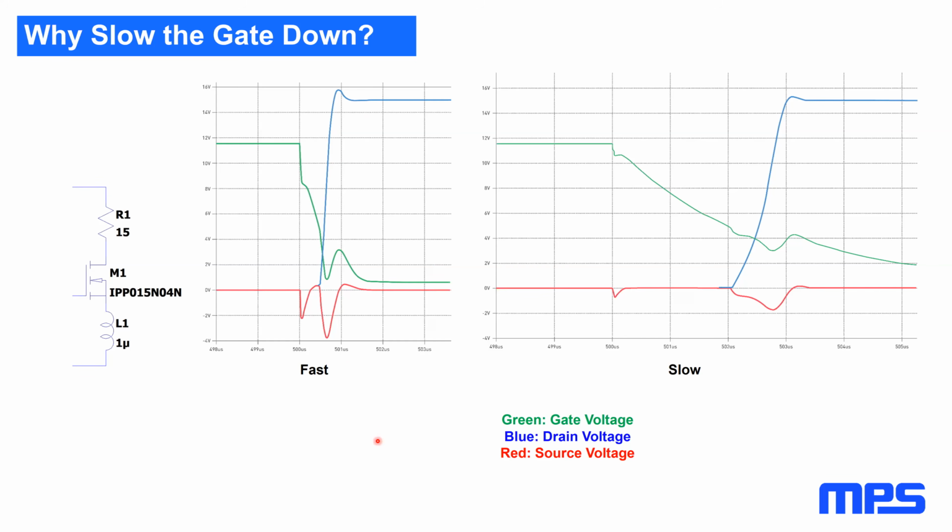Fair enough. Let's see. How to select a MOSFET for a switching application and continue on applications. I've sort of covered that in various pieces. The voltage rating with margin, the current rating, but primarily RDS on as it relates to power dissipation.